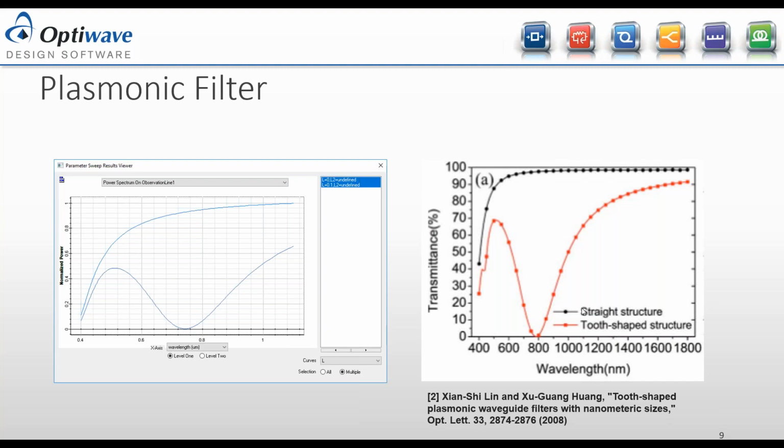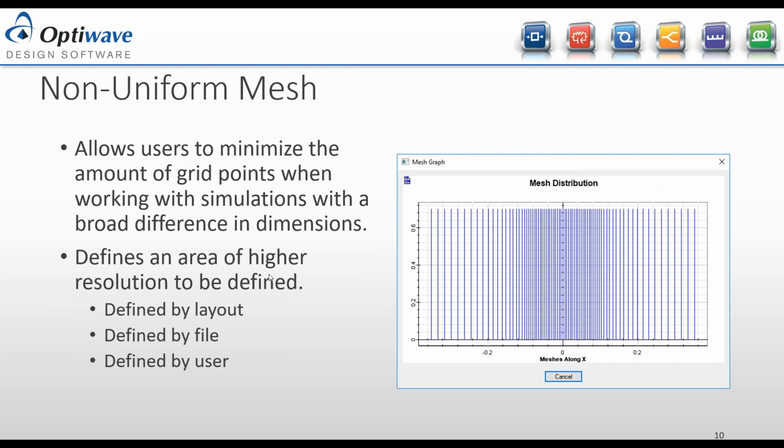the left, and we can see the results from the paper on the right. Now there is some difference in terms of what the maximum transmittance is between ours and theirs. There's a number of reasons for that, one being the resolution sizes that were chosen, the lengths of simulation, but the other issue is that the results from this paper, we're using a Drude model, we're using the Lorentz Drude, so we're actually modeling slightly different materials with different properties. They're both silver, but are over different wavelength regions and that. But we do have the general transmittance results for that.